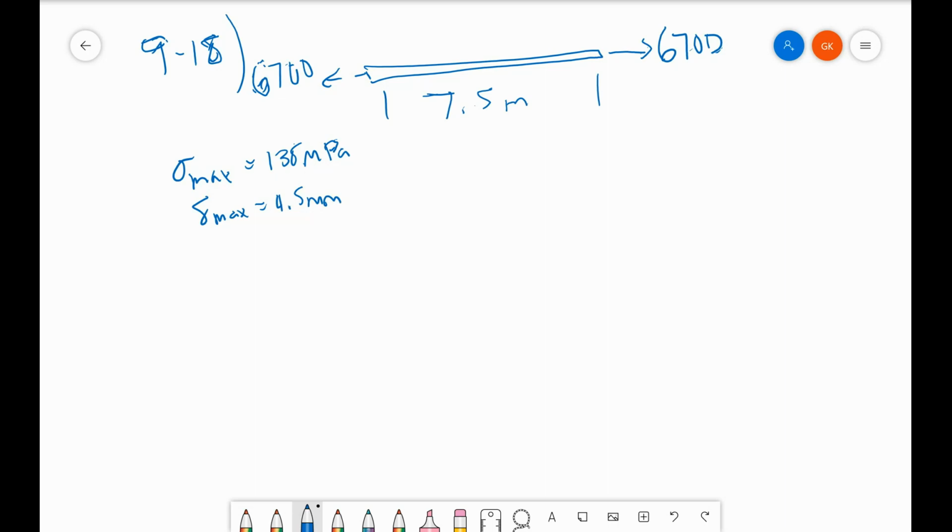Compute the required diameter of the wire. Neglect the weight of the wire. And it says to use a modulus of elasticity of 207,000 megapascals, a proportional limit of 234 megapascals. Okay. So E equals 207,000 MPa. And the proportional limit is equal to 234 MPa. Okay. So we need to find the required area, or required diameter of the wire.